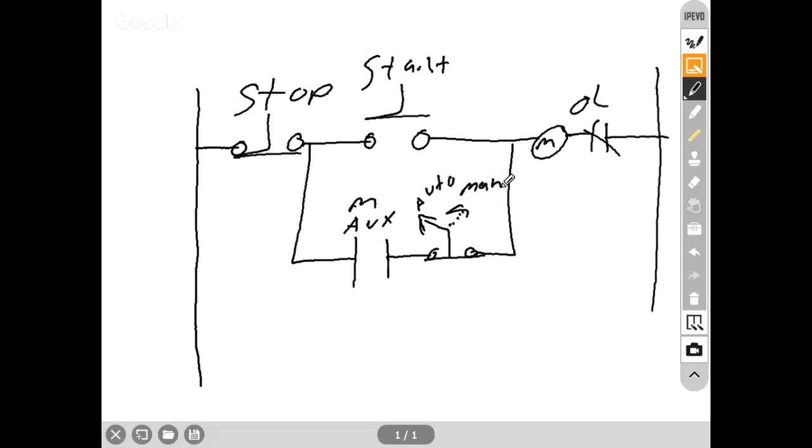We just make it shut off. No. Well, this was just a start-stop, right? So if I turn this and this opened up, what would that now be? Jog? It'd be a jog. Why didn't we do jog like that? You'd have to hold down the button, right, just to get it to go. Because I wanted you to use a separate jog button.